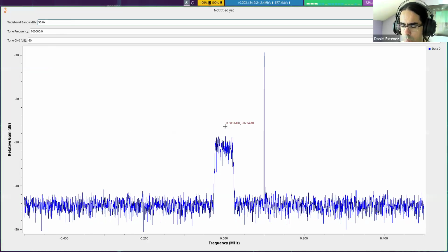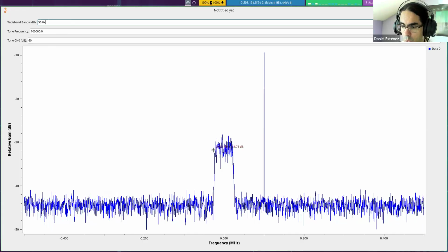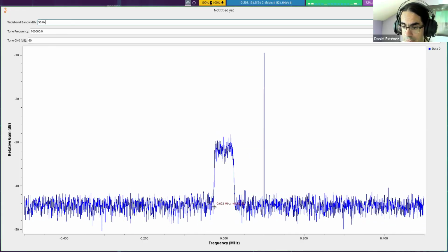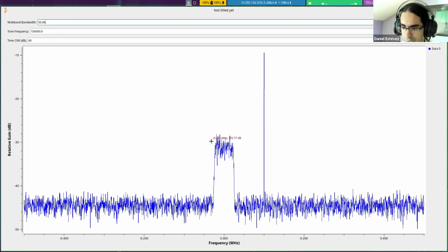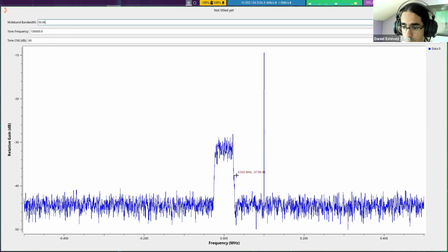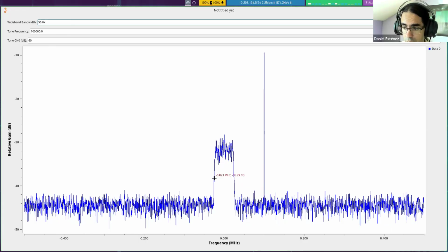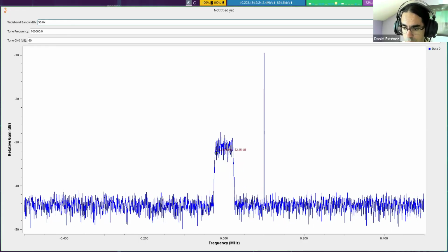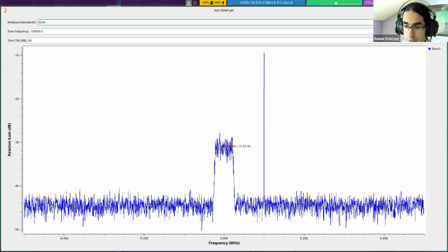But because we are changing the bandwidth, the power is distributed over all the bandwidth which is occupied. If the noise is narrower, then we distribute the power over a smaller bandwidth. So basically, everywhere here, we get more power, or power density, if you wish.